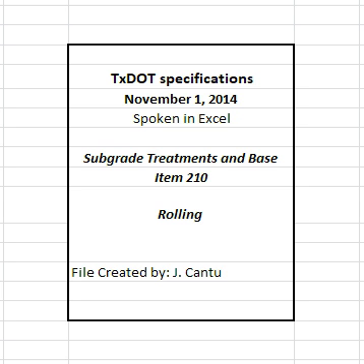2. Equipment. Use any type of roller to meet the production rates and quality requirements of the contract unless otherwise shown on the plans or directed. Use equipment that meets the requirements of this item when specific types of equipment are required. The engineer may allow the use of rollers that operate in one direction only when turning does not affect the quality of work or encroach on traffic. Table 1. Roller requirements. See table in specifications. 1. Unless otherwise specified in the contract.